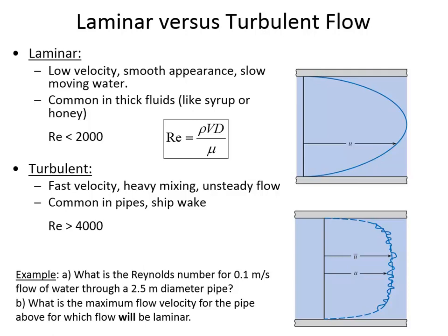And what they're representing with the velocity distribution here is that there's a lot of variation over time. If you look at this particular location right now, it looks like it's a little bit less than the average. But if you look at this location in 3 seconds, it may be a little bit faster than it was 3 seconds prior. This dashed line is representing the average velocity profile over time. And you'll notice instead of having this bullet shape that there is for the velocity profile, it's a lot more flat in the case of turbulent flow.